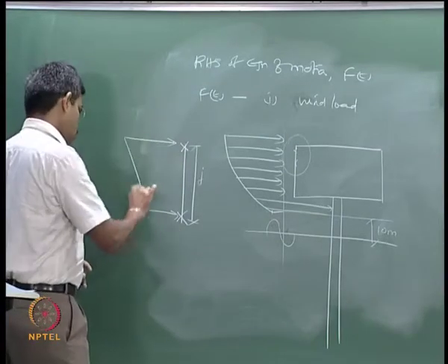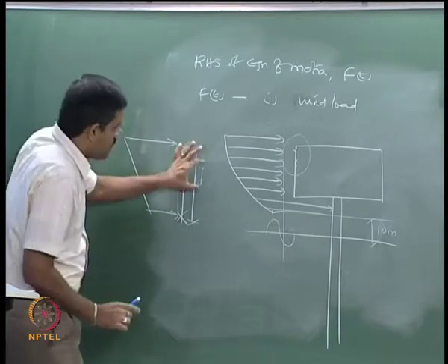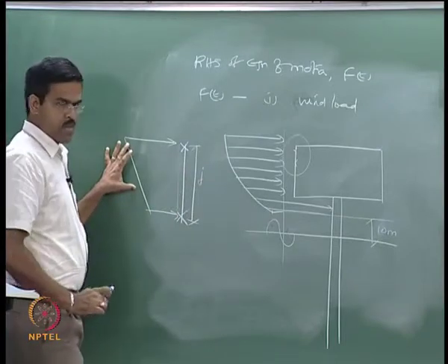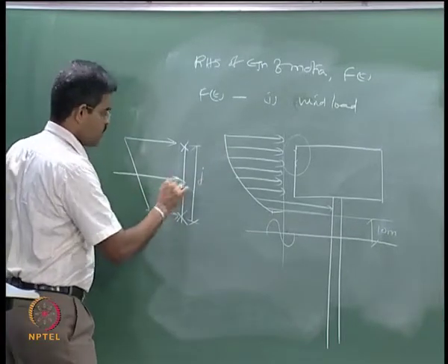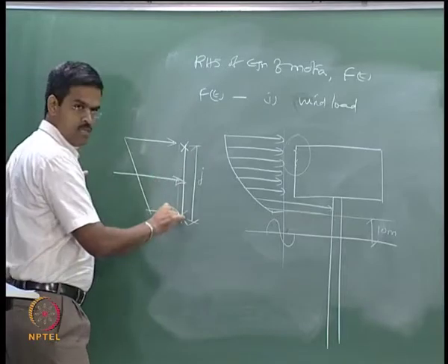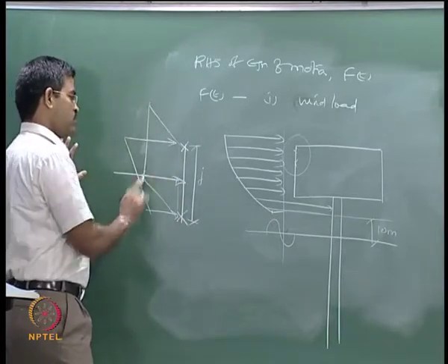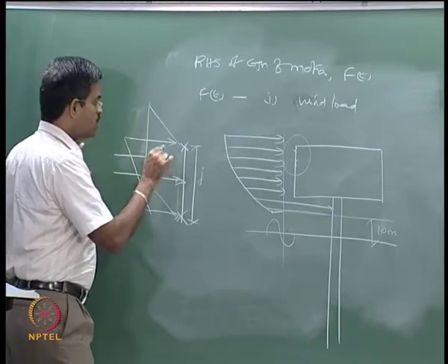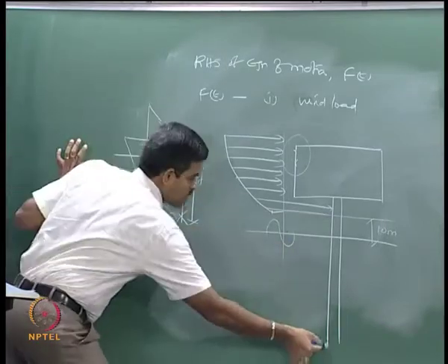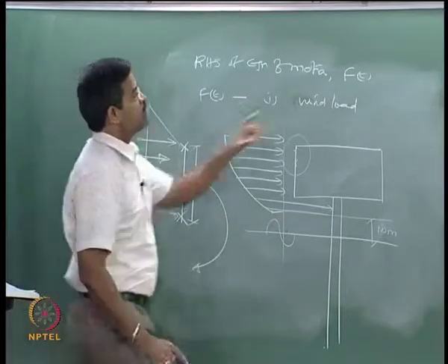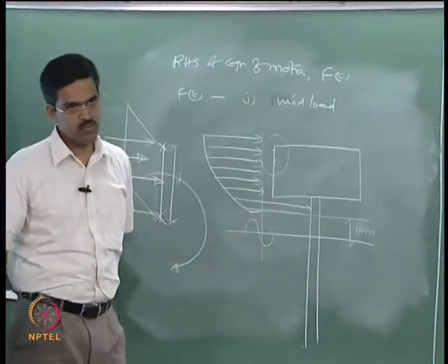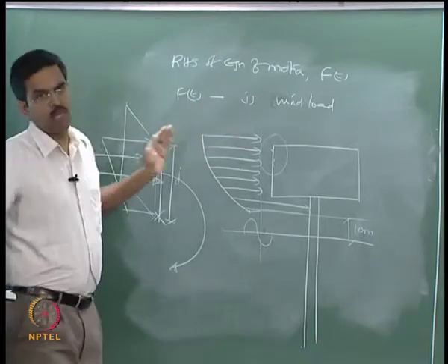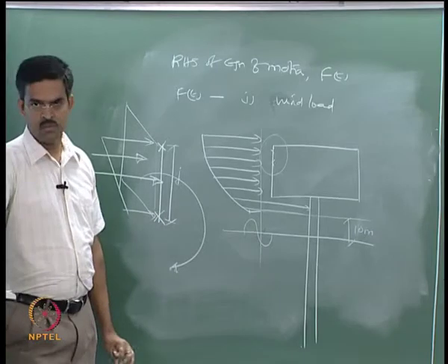So I will assume this to be linear in between, because the length of the element is so small, I can linearize it. I can get the Cg of this, I can get the multiplier and length of this, I know the projected width of this, I get the area. For that force, the distance of that Cg from the base will give me the moment, which is f of t. I can do this for n number of elements and keep on adding them. Is that clear?